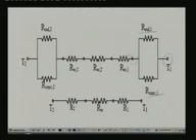So this is the temperature of the surface of the wall inside the room, TS1, and from this point to this point the heat transfer is taking place through the wall. So you have 3 different layers. This is the conductive resistance of layer 1, conductive resistance of layer 2, conductive resistance of layer 3. The mechanism is conduction and all the resistances are in series. So this is the temperature of the surface of the wall inside room 2. Remember that at this point again the heat transfer takes place in parallel by radiation to the surrounding surfaces and by convection. So again you have a parallel network here. The whole thing is a typical heat transfer network for the problem discussed now.